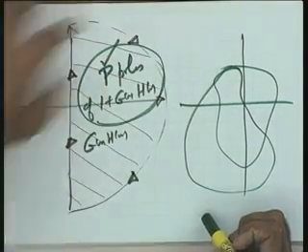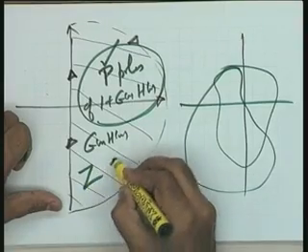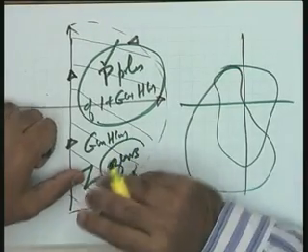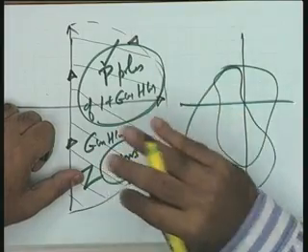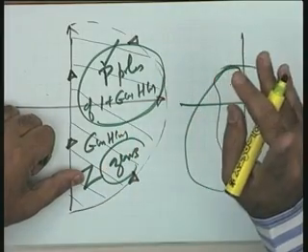So, it means if there are P poles of 1 plus GSHS in this particular region, and let us say Z zeros. What are the zeros of 1 plus GSHS? Are you able to appreciate this point, that zeros of 1 plus GSHS are nothing but the closed loop poles of the system? Your zeros are not known to you.